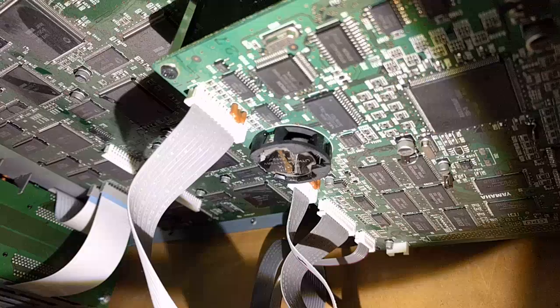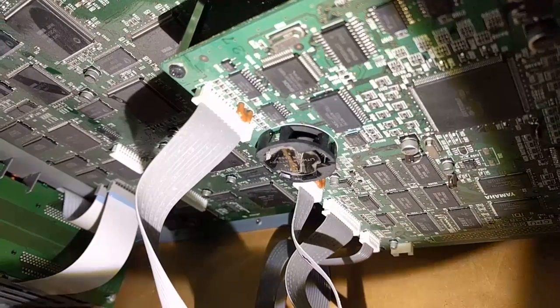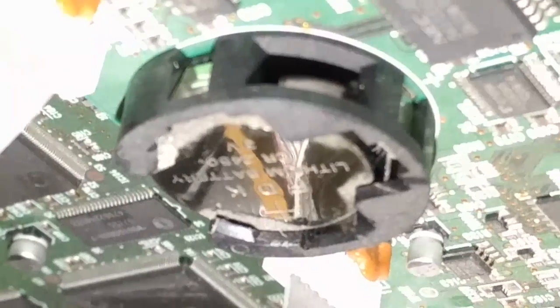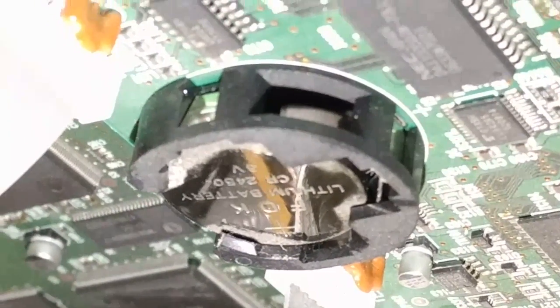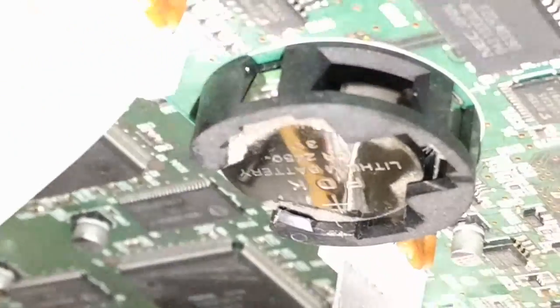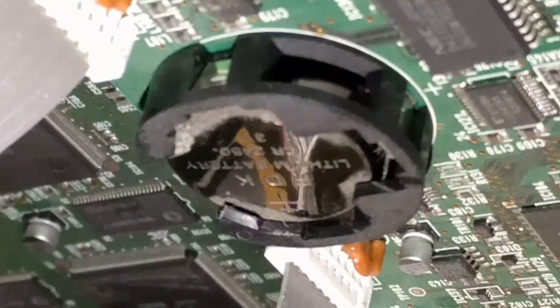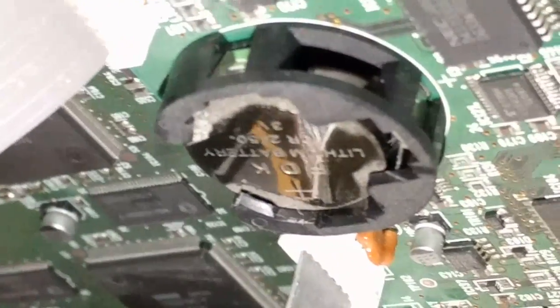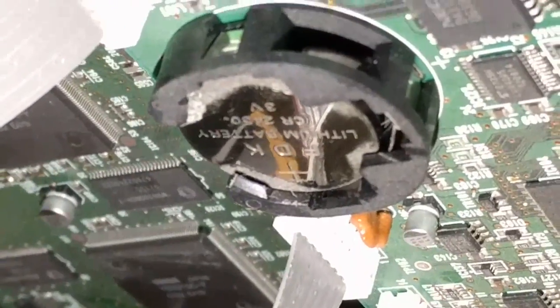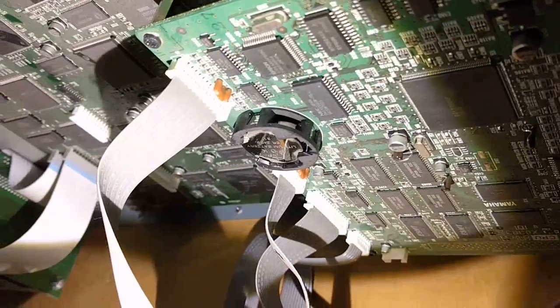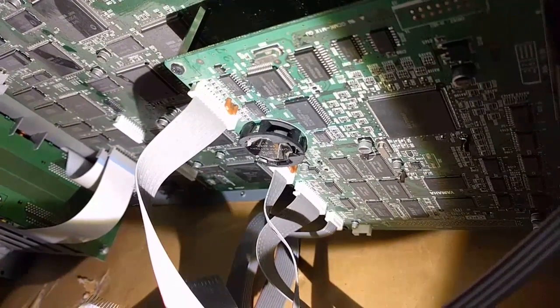Here's the battery board in the DM2000 Yamaha mixer console, and you can see it's actually not a CR2032, which is the common 3-volt battery you find. It's a CR2450, from what I can tell here. And I don't have one of those. It's very uncommon. So I'm not thrilled that I can't change that, but also, what are you gonna do? So hopefully somebody else can learn from this video to get one of those first.